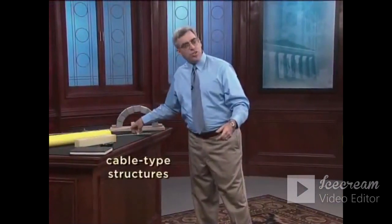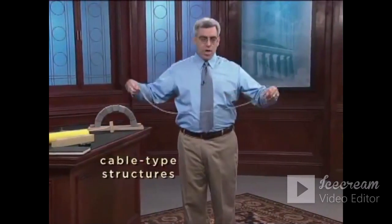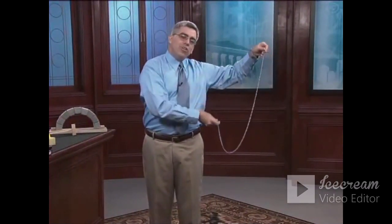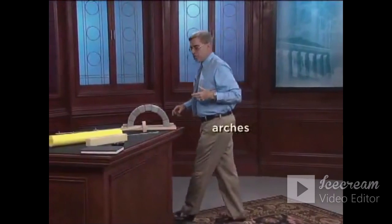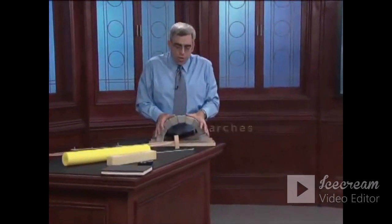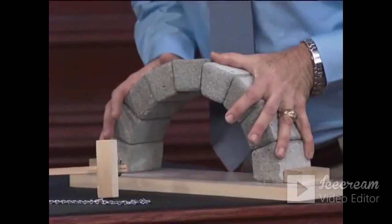Cable-type structures, as we've seen in our model of the Brooklyn Bridge, are flexible structural elements that carry load principally in tension and change their shape in response to changes in applied load. Again, just as we saw in our Brooklyn Bridge demonstration. And finally, arches. These elements can span horizontal distances, but because of their unique shape and unique supports, they carry load primarily in compression.